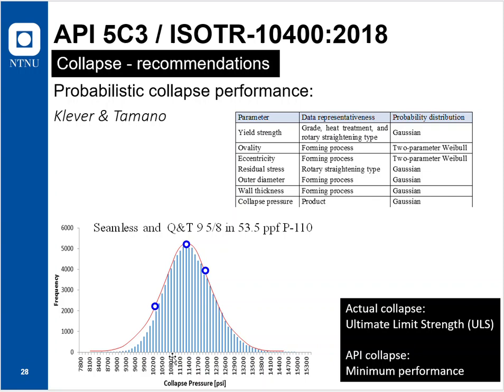What we do is make our own decision with regards to standard deviation in this case, saying that okay, it is probable that 2.5% of the pipes will collapse given the strength of say 9,600 psi here.